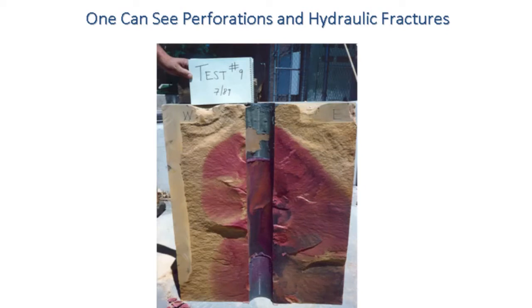And there's the overall picture, and what we found out was that the computer model said that the cracks should all be semicircular or elliptical, and they should all propagate at the same rate, and we should have a symmetric result, and we didn't. But that's because we're working in a natural material, where there are variations in the properties point by point. That wasn't man-made sandstone, it was natural sandstone. So even though we could control in a laboratory all the pressures that we were applying to that block, we were squeezing it in 3 directions with the same stresses that would exist downhole. We still didn't get results that perfectly matched the computer models. Close.